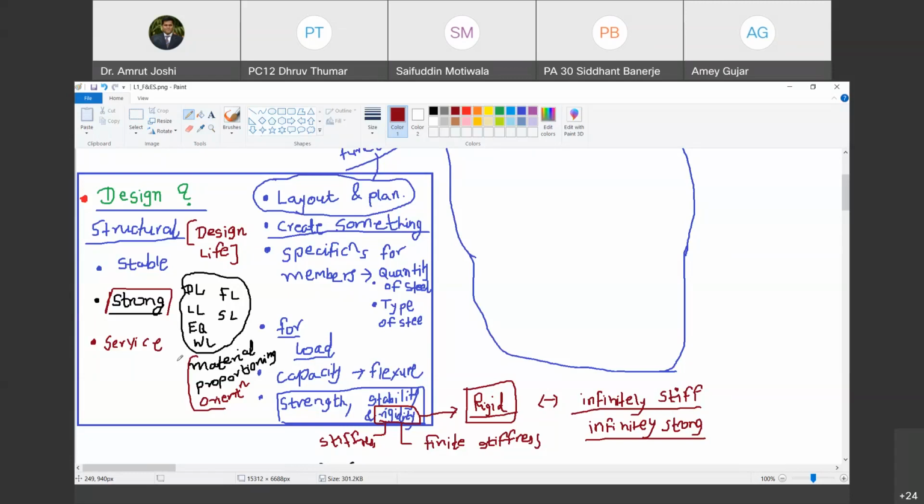So therefore, the serviceability is contextual. We can permit those vibrations on footover bridge. We cannot permit those vibrations on residential building. We cannot permit those vibrations on a hospital building. Hospital building में तो और ज़्यादा strict है because you have a CT scan machine there. If your floor itself vibrates to that extent, it is going to mislead the results, isn't it?